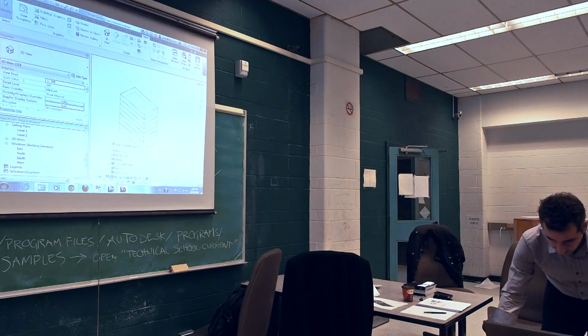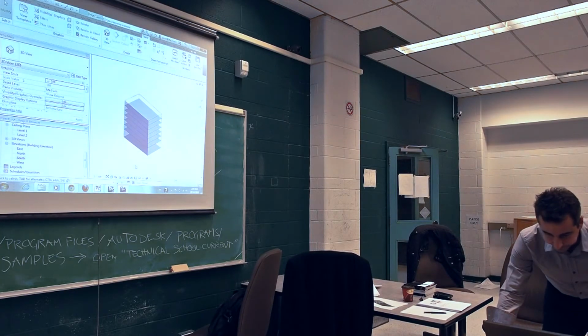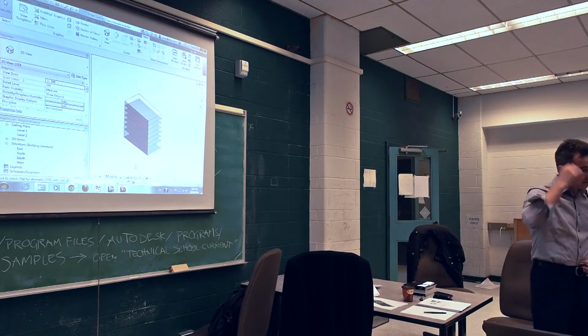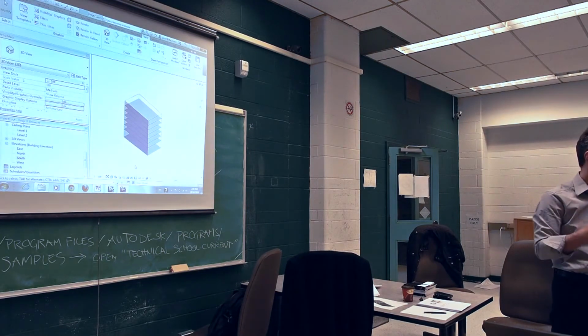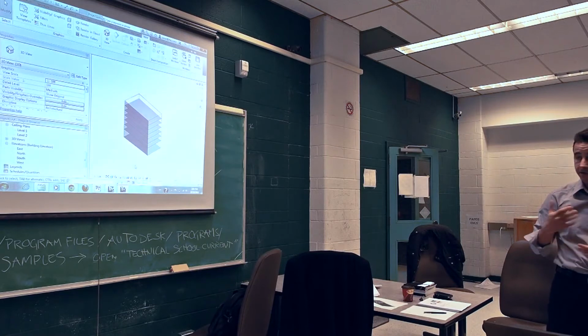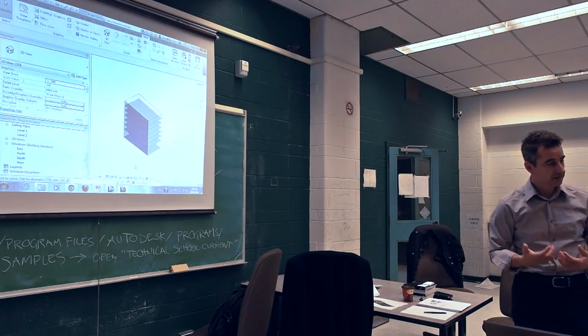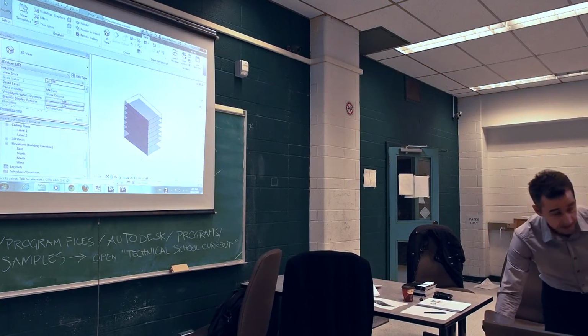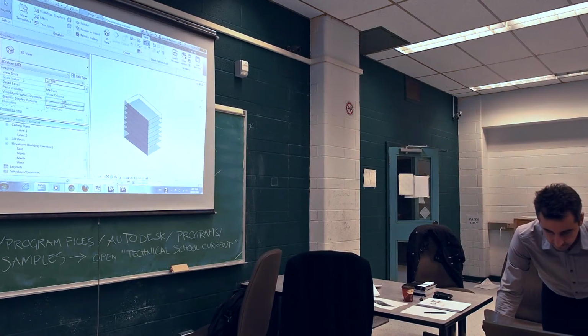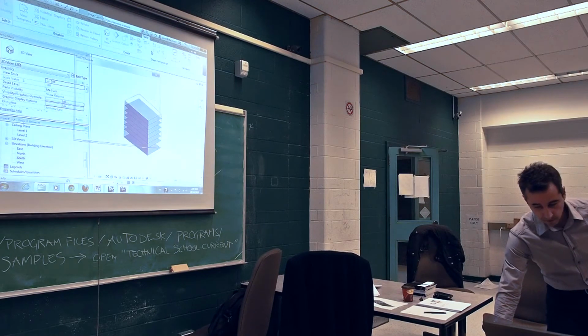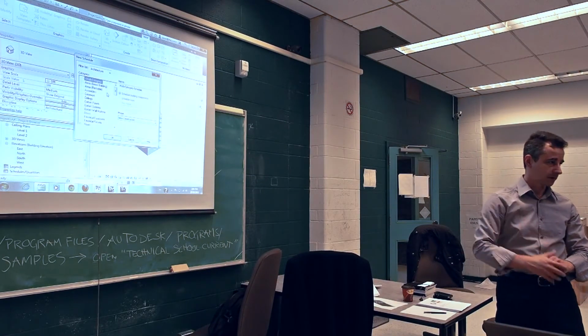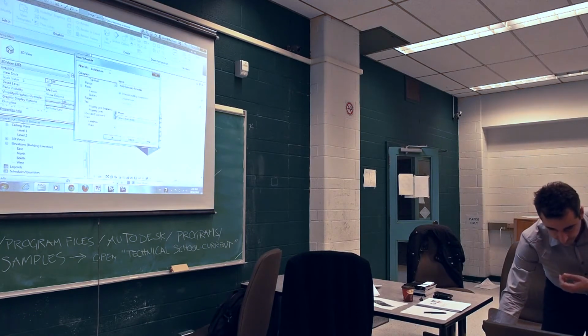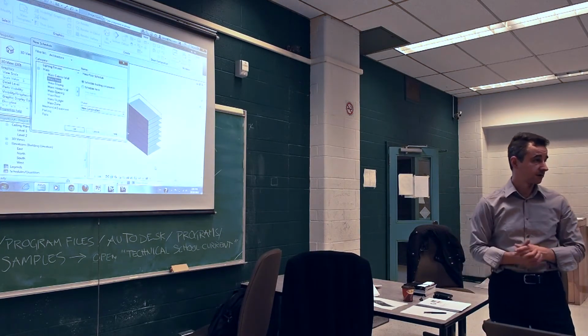And just to enhance the view a little bit, I'm going to shade this. And at this stage, although I didn't do too much, I just have a footprint which I extruded and I created some floors. I can extract information already from this model. And the first one, the most obvious one, is the areas, the square footages, and that has to do with schedules. So if I go in my schedules, which is under the View menu, the first one, schedule quantities. What do I want to schedule? I have a whole list of options, and really in this case you have to scroll down to mask floors, because I created mask floors out of this object.